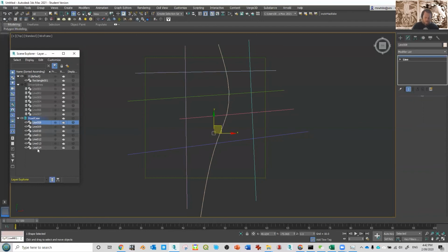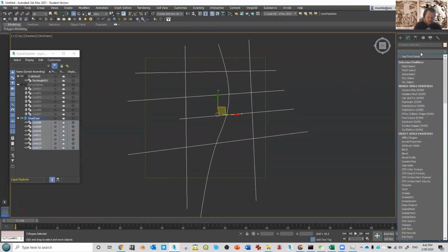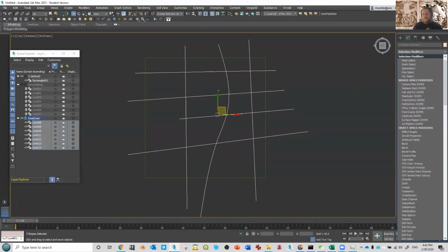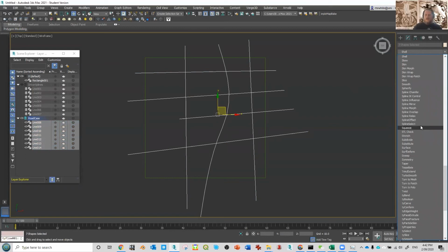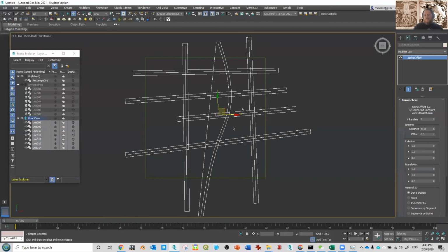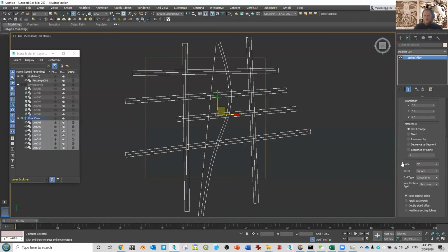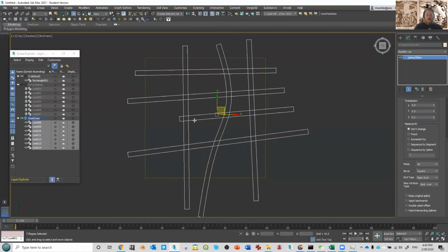And I can select all of them, select them in here, and now I'll apply the spline. We need a button for spline offset. I don't have the option to make a group from the layers. How did you get that little plus sign there? Okay. I'll just do the spline offset and then I'll come back to that. So spline offset. And now I would set those settings, so closed, no, open butt, and don't keep original geometry.